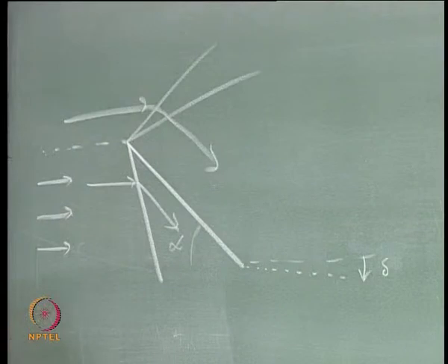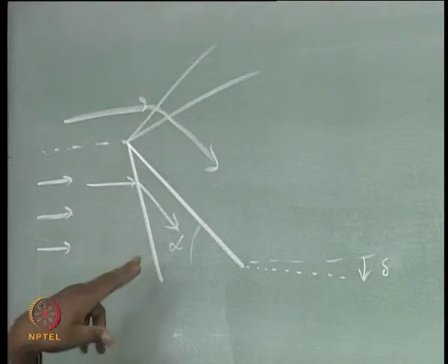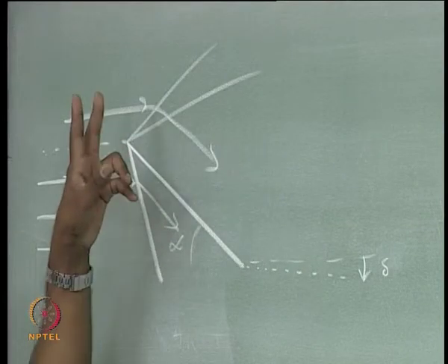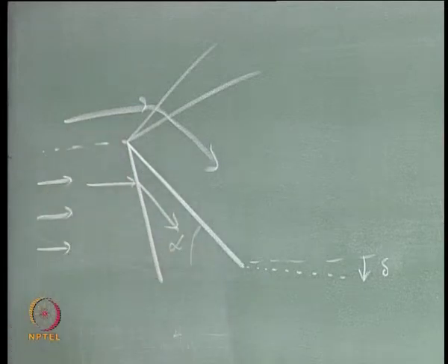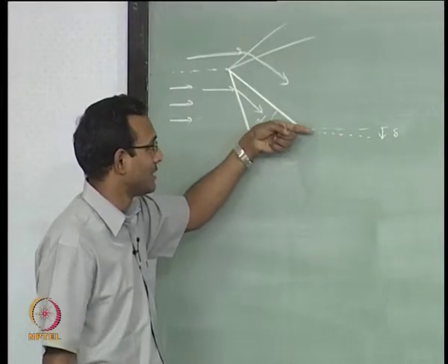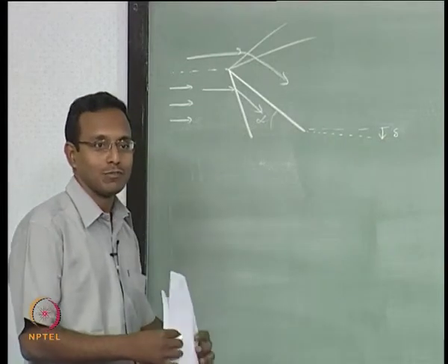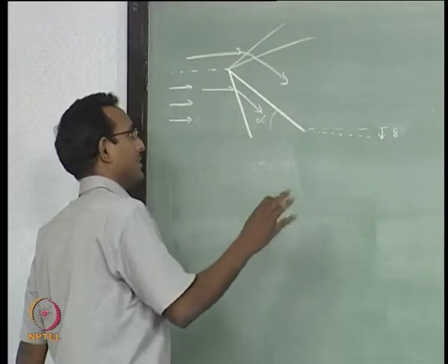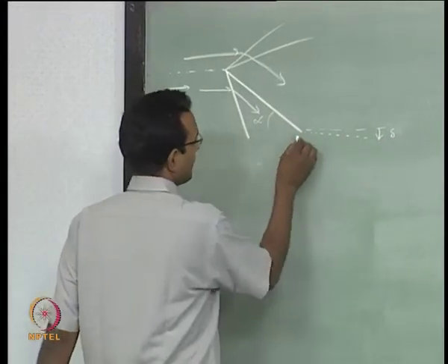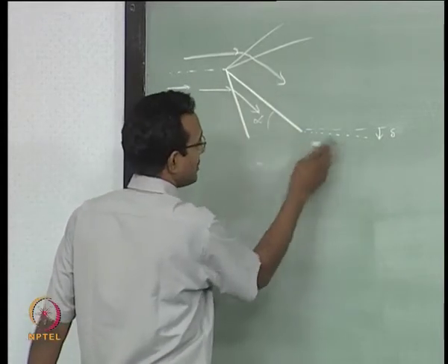If you think about it from aerodynamics point of view, this is an airfoil at positive angle of attack, it is going to produce lift, which means there should be a downwash. So I am going to say that there will be a small downward component to this flow after it leaves the airfoil. That is the way I am thinking about it, which means this top flow is going to see a compression wave here.